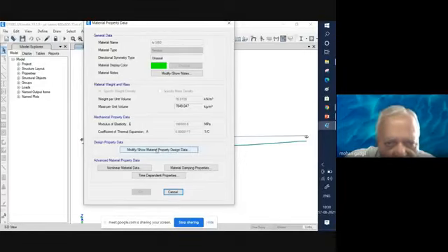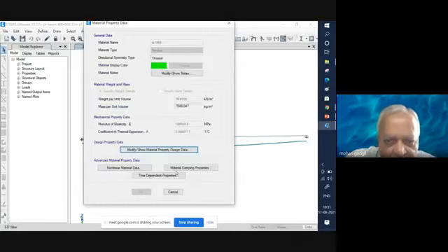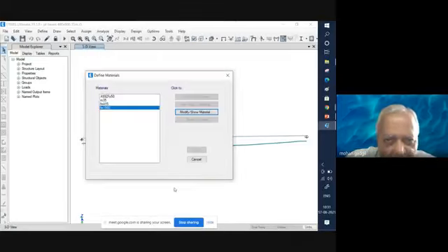If you consider the material property of it, see its minimum yield strength is guaranteed at 1689. Can you see this figure? 1689, and the minimum tensile strength is 1860. These are all in MPa, that is Newton per mm square. I am now considering this particular data for material. So I have got the material data.